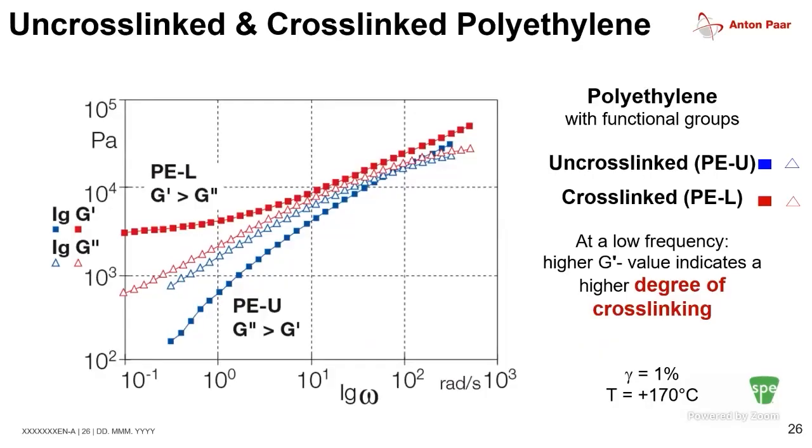Now, likewise, if you're comparing materials, if the sample does have structural cross-linking in it, you can see in the case here of a polyethylene with different functional groups, in a cross-linked and uncross-linked material, they behave very similar. They have roughly the same elastic contributions and viscous contributions.